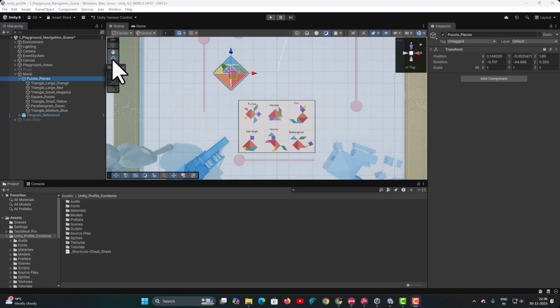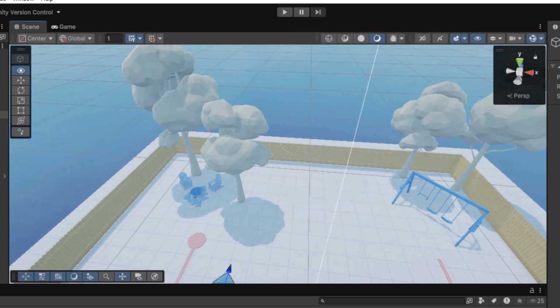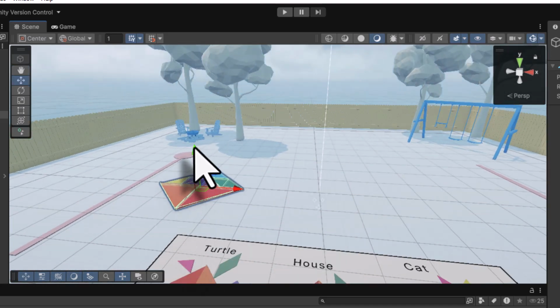The axis means, when you are moving, you can see in this gizmo, X is colored red and this represents the movement from left to right, and Z is represented by blue and this represents front to back. And now if I right click and tilt up like this and press Q to come down, you can now see a green axis here, and this green axis represents bottom to top movement